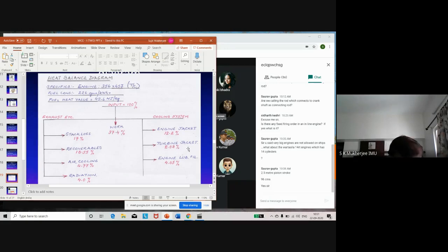We had a situation on board where it was cooled with water and then cracks started forming. So we called the expert from Sulzer; it was a Sulzer turbocharger. The expert came and told us to stop putting any water for cooling and introduce these pellets. So he brought pellets made of clay.